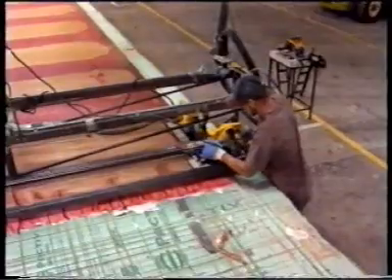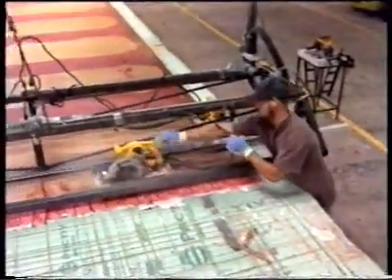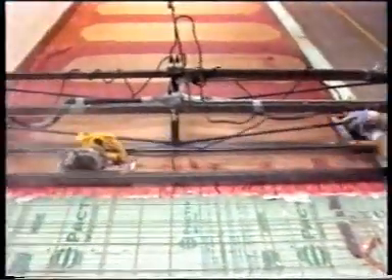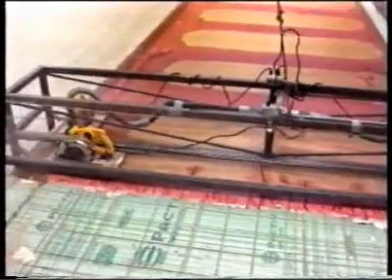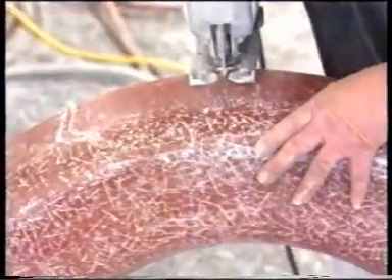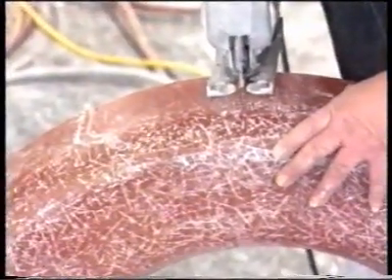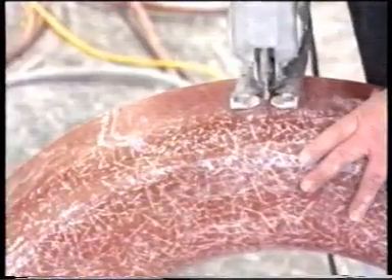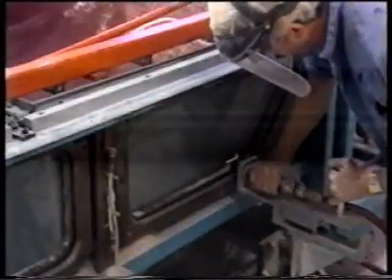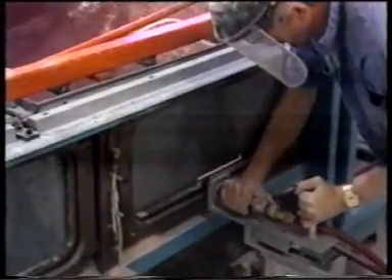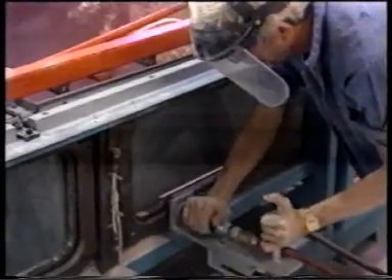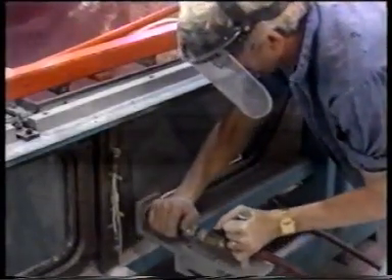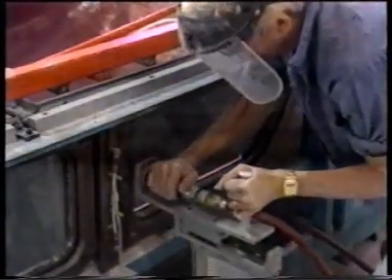With circular saws, the speed range is broader still, 2,000 to 10,000 feet per minute. Blade speeds of 2,500 strokes per minute are suggested with saber saws. Manual and machine routing have been effective with fluted carbide milling cutters and carbide-opposed helical router bits.